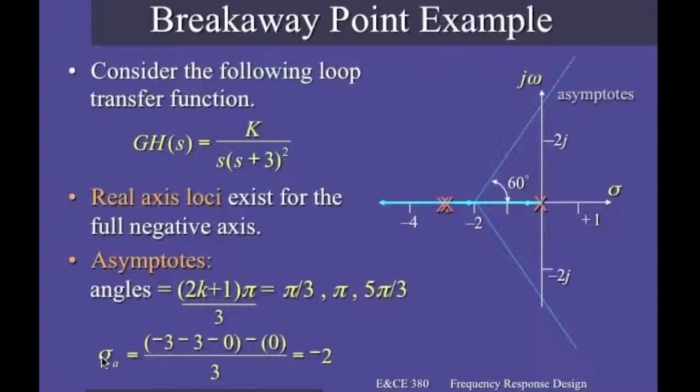Here there is a solved example for a transfer function in a factorized form, and it is also in the pole and zero form. We have 3 poles. One is at the origin, as you may immediately understand from the factor s. And 2 are at -3, because there is a multiple root, as you may understand from the squared factor